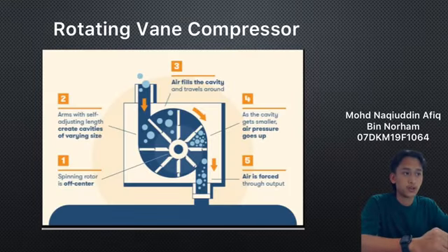We discuss the rotary vane. A rotary vane compressor is like a rotary screw compressor, but instead of a screw, the vane is mounted on a rotor and rotates inside a cavity. Air is compressed between the vane and its casing and pushed out through different exhaust ports.